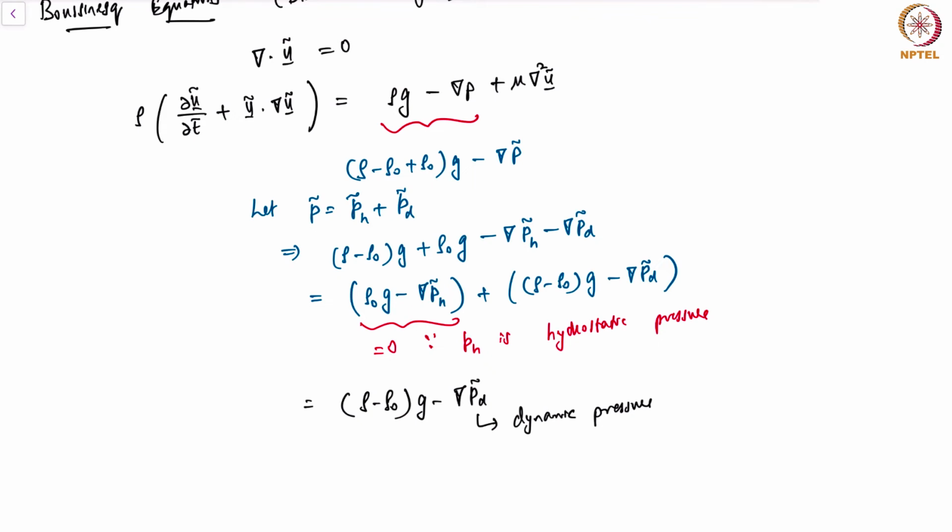Okay. Now, in the Boussinesq approximation, what we do is we say that the density variations are only important in the gravity term and in no other term. So one can systematically expand, like for example, in the inertial terms you have density rho. This rho can also be thought of as some mean value rho naught.